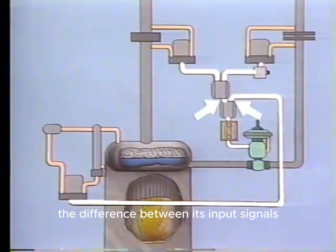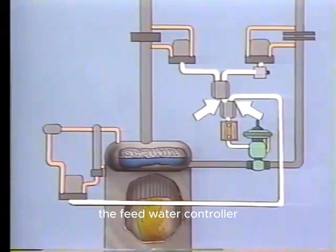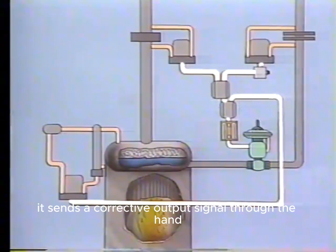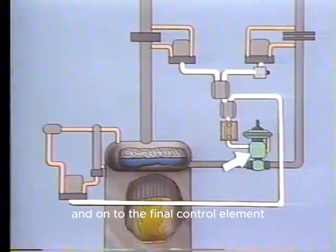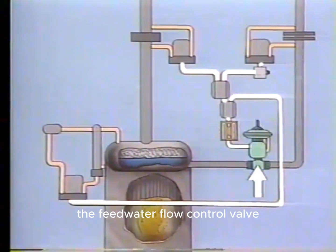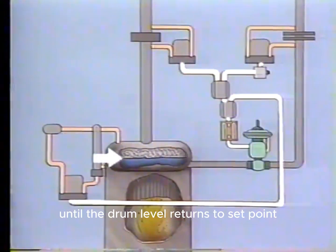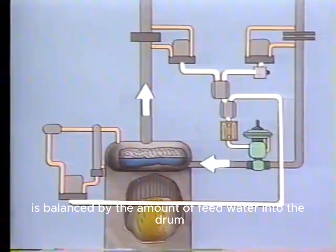After computing the difference between its input signals, the feed water controller compares the difference against set point. It sends a corrective output signal through the hand auto transfer station and on to the final control element. The final control element repositions the feed water flow control valve to regulate the feed water to the boiler drum. This process continues until the drum level returns to set point, and the steam flow out of the drum is balanced by the amount of feed water into the drum.